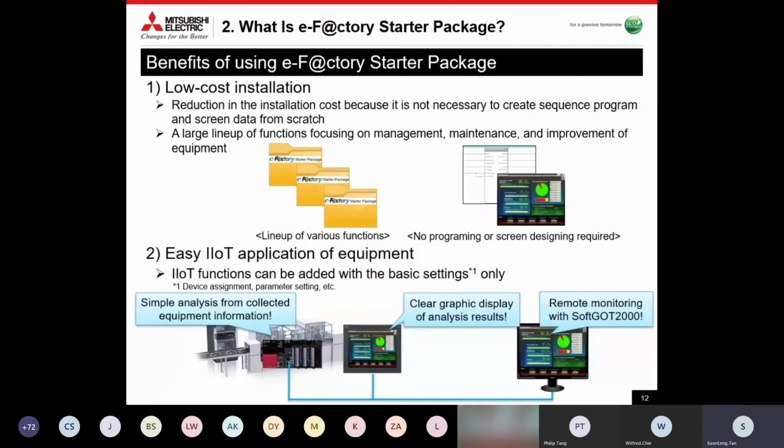So what are the benefits of using this eFactory starter package? The first benefit that you will see is low cost installation, because you don't need to create the sequence program and screen data from scratch just to do your visualization or analysis. Everything is done for you in the template. You just need to download the project into the PLC and HMI, connect to your machine, and you can get IIoT started. Inside here, you will see functions that focus on management, maintenance, and improvement of your equipment.